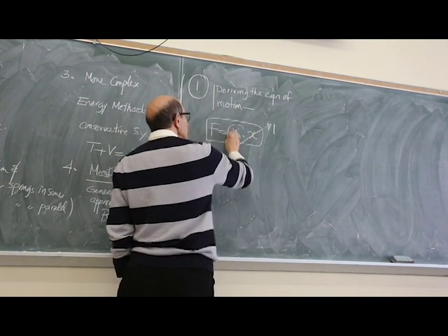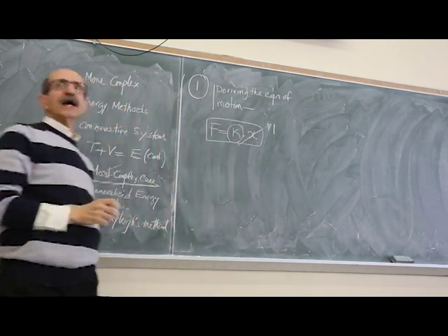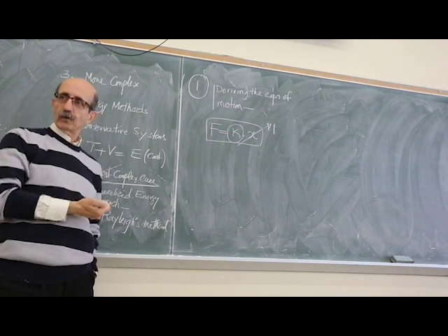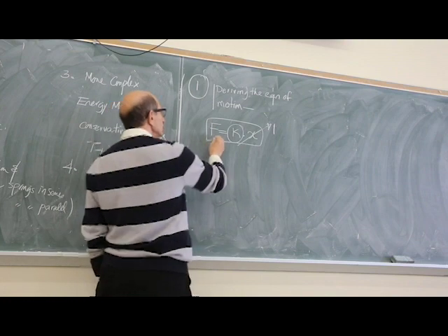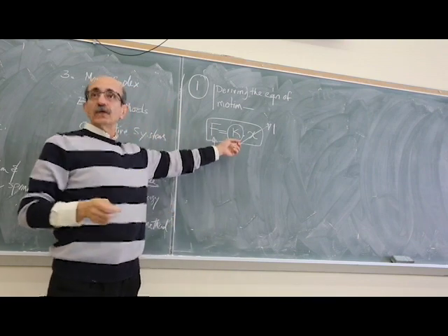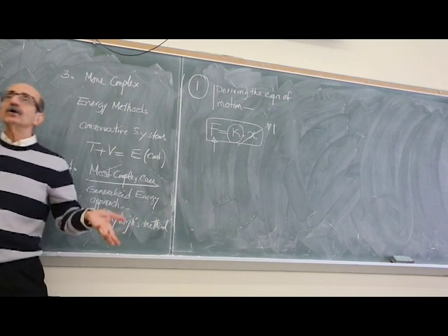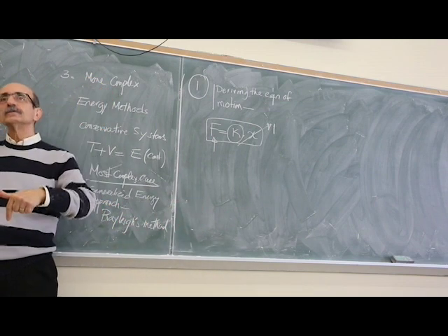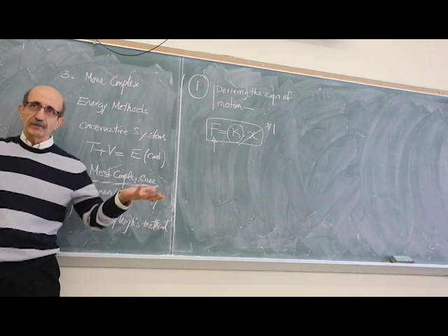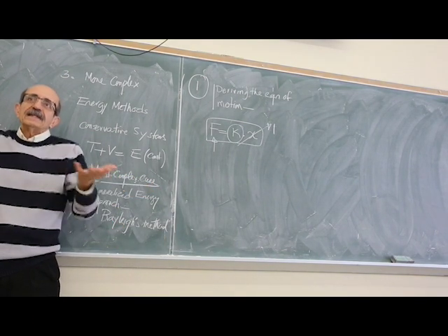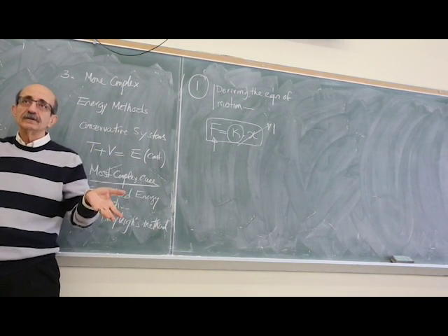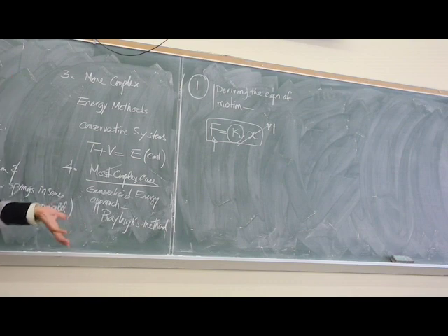So this ability of the structure to resist force is equal to the applied load. In order to find the stiffness in a system, all you have to do is apply a load, find the displacement as a function of whatever parameters you have, and in that expression, if you set the total deformation as 1, the force becomes equal to the stiffness.